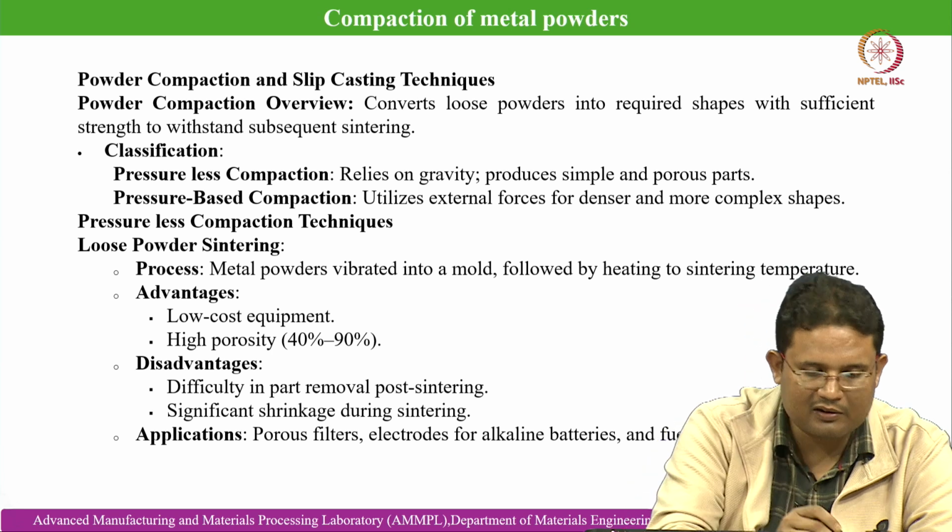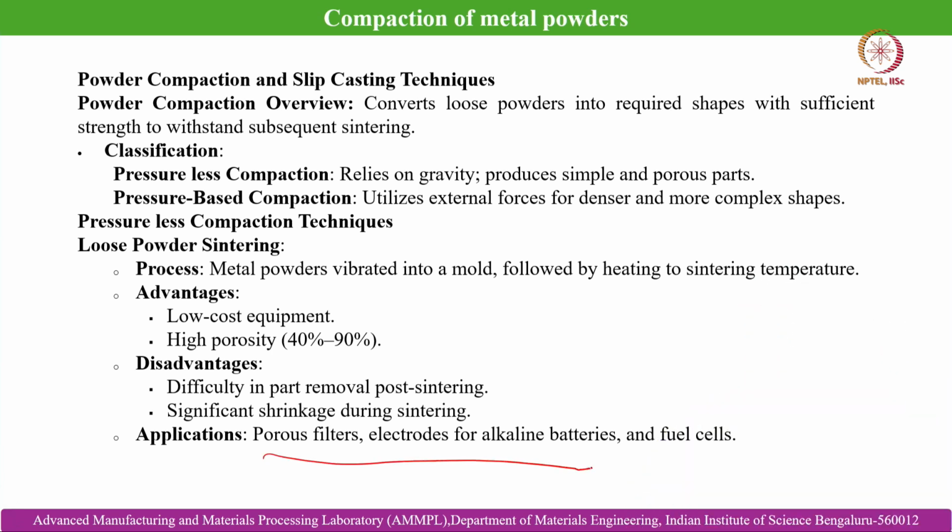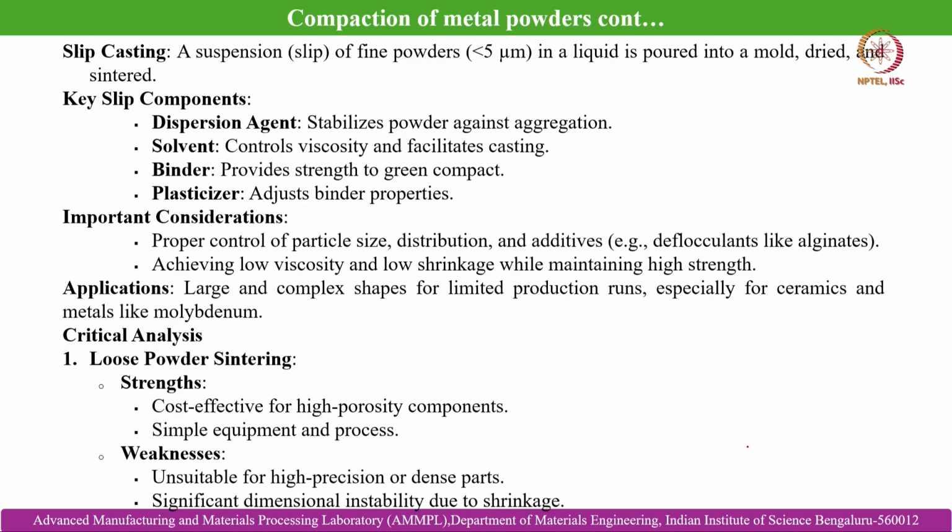The applications, as I told you, are porous filters, and electrodes for alkaline batteries and fuel cells. Okay. And then there is another example of a common powder metallurgy technique, which is slip casting, where a suspension or slip of fine powders less than 5 micrometer suspended in a liquid is poured in a mold, dried and then sintered.